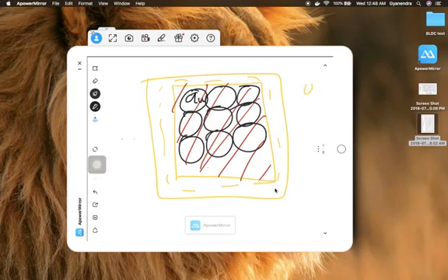Now you will see one very interesting fact: there are areas which are not utilized even after placing the windings very close to each other. So we cannot utilize 100% of the window area for placing the windings. Only a few percent of the window area can be utilized. That factor is called kW. kW is the window factor, which is defined as the percentage of window area which you can utilize for placing the conductor.